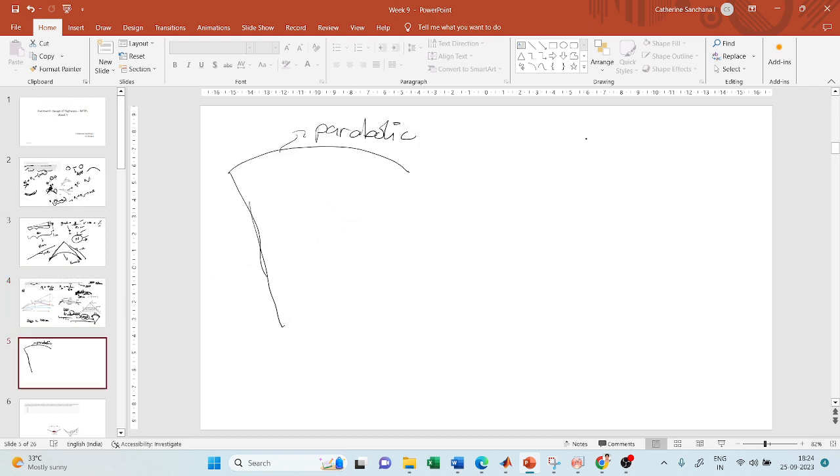Here also it is related to the length of the curve, and you have a formula to find out the length of the curve or the stopping sight distance. If you have one, you can find out the other. So one formula for length of the curve less than SSD, and one formula for length of the curve greater than SSD.